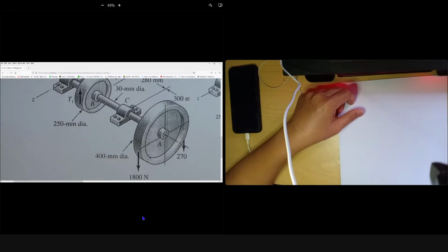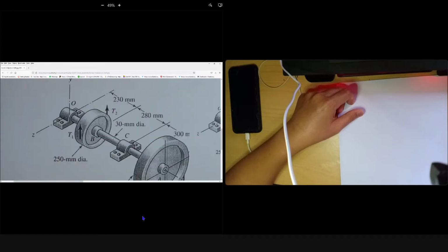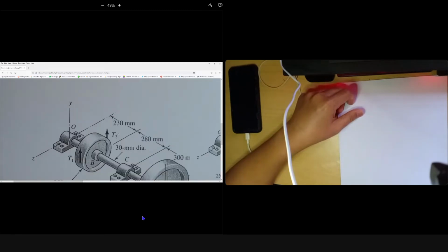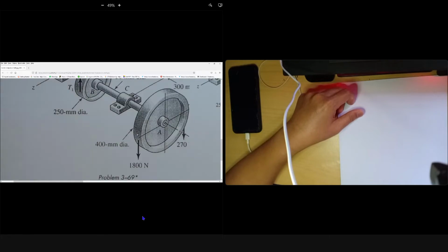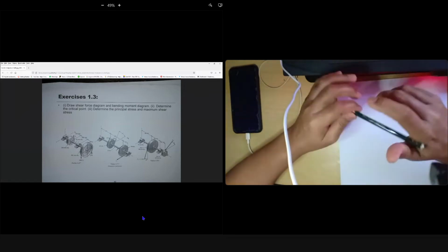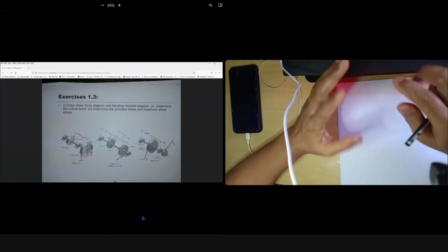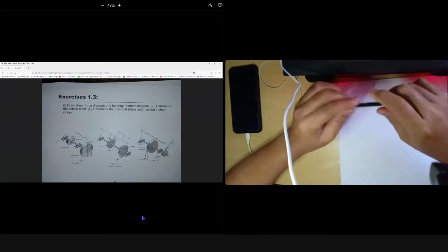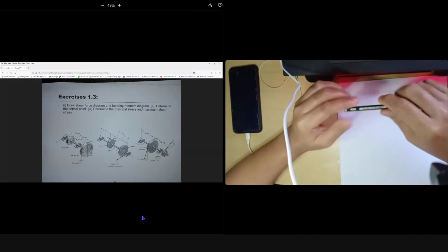You can solve this kind of problem, like how to work out the tension. Tension 2 is 0.15 of tension 1. You can get the free body diagram, right? So you draw the shear diagram and moment diagram, and they must be right. If your free body diagram is wrong, the value of everything in your shear diagram is wrong. Your force reactions will be wrong, so your shear and moment diagrams will be wrong. Be careful. You must be correct from the starting.